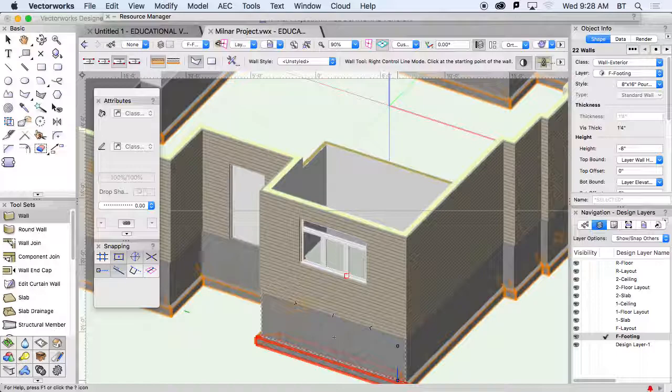So I set it at the same reference point for both the footing and the foundation. And from that reference point, which is the top of footing, which when we're in construction we use as a reference point, the foundation wall goes up. From that top of footing, the footing goes down. I forgot we did layer elevation. Yes. Okay. That makes sense.